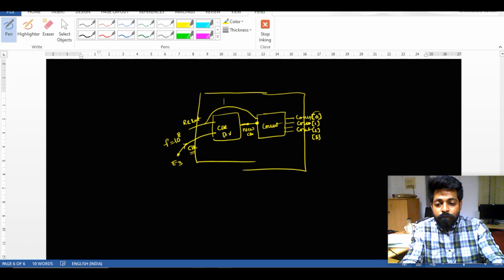So now these 4 bits you want to locate at 4 locations. As we see, there are 4 LEDs on the FPGA. Let us see where they will be: N14. There are 4 LEDs. One is N14, J13, K15, and H17.